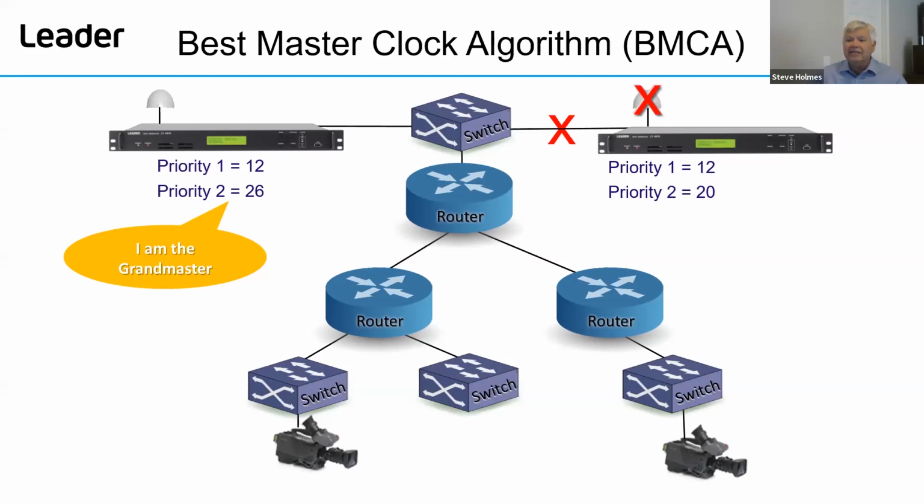So PTP is, in fact, going to go away for whatever the cycle time has been set for. Typically, it's 3 messages, and you're going to get 3 announce messages before the unit on the left is going to say, hey, you're gone, I'm going to jump in here, and then it will jump in. All the units, the slaves that are locked to it, will still be freewheeling through what they're doing, so there shouldn't be a big disruption in what's going on, but it will have to be a resync, which is not huge, but there is a little bit of a loss in going through that.